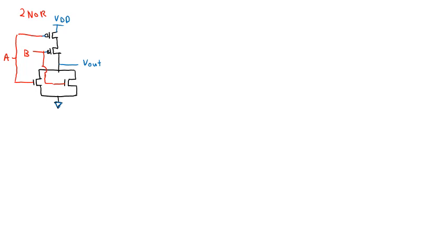First, maybe you can concentrate on the poly lines. For the PMOS, you have this poly in series, and then overlap with the diffusion, or we call it a P diffusion. Just put it with the green color. Just overlap of both. This one. Okay, this is a PMOS in series.